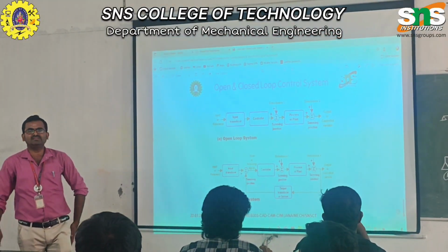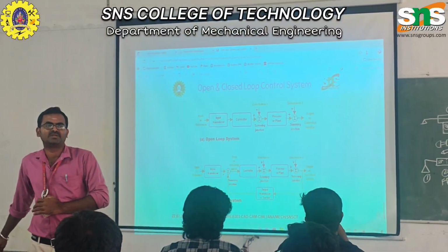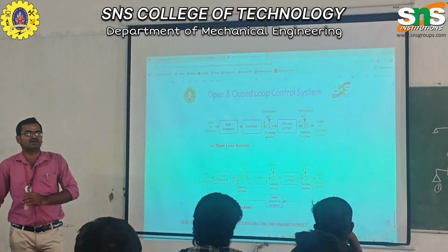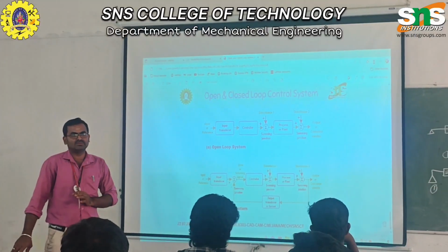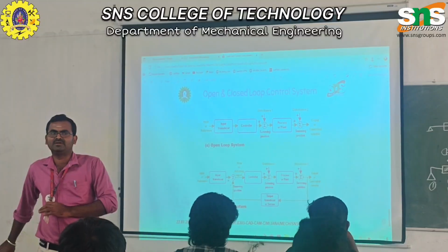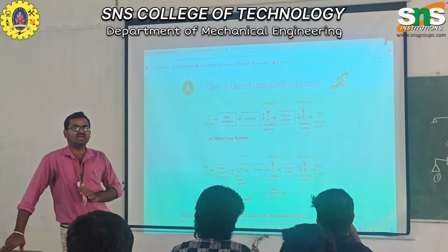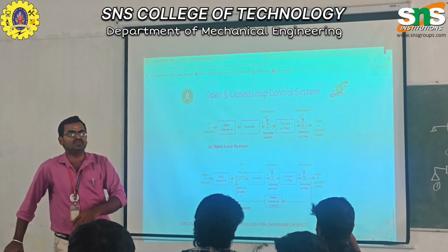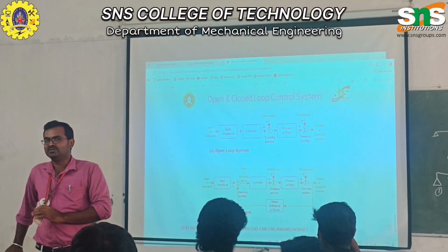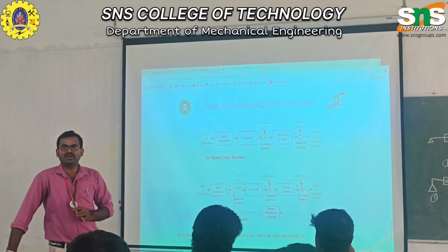The pneumatic system is the next example, for an open loop system. There we produce compressed air as the fluid medium. It is directly controlled by the regulator, the FRL unit, so we can directly regulate the pressure level using the FRL unit, but we do not use a sensor. After the operation, the compressed air is sent directly into the atmosphere with the help of either a muffler or a quick exhaust valve. So there is no continuous cycle or closed loop in our pneumatic system.